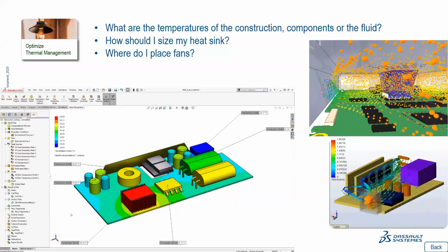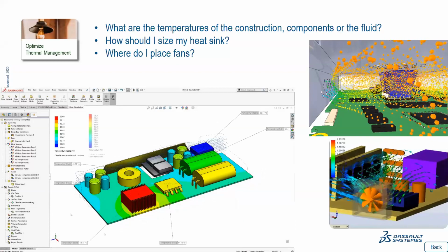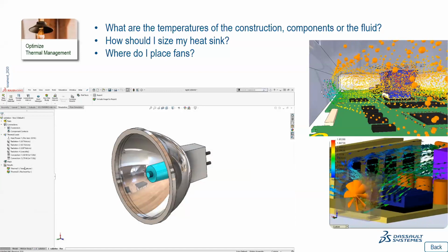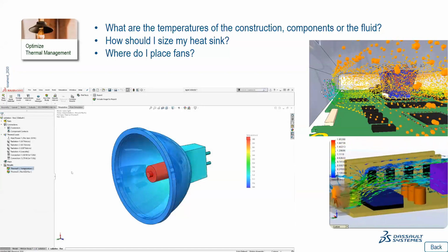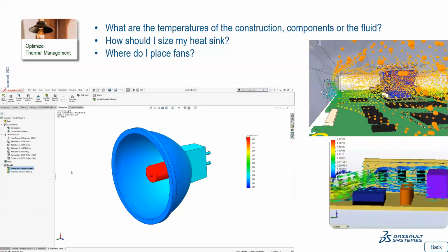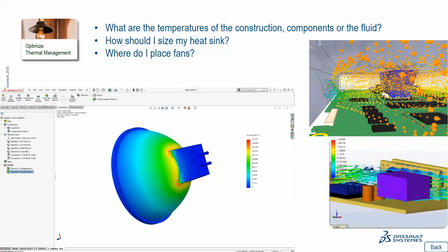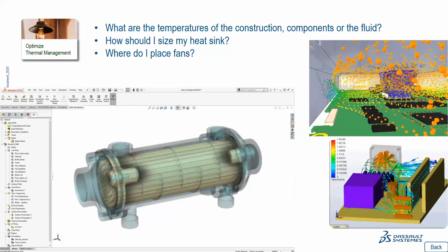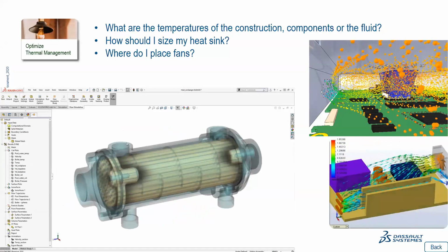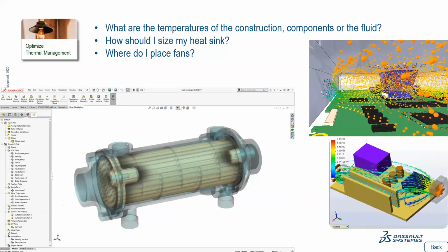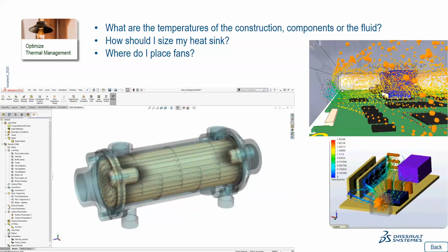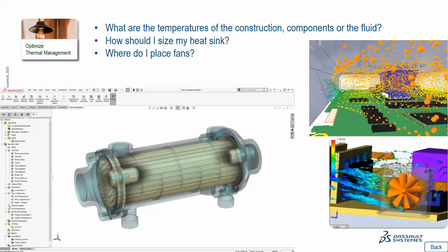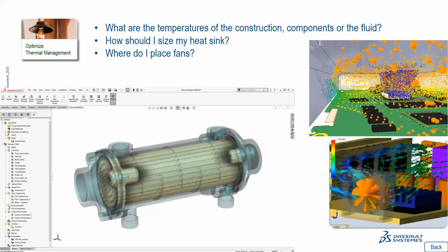Or also in the high-tech industry, everything which includes electronics will generate heat. So when you have this type of device, you can say, okay, I have to put one fan, maybe should I put two fans? Where is the best location to put the fan in my device? So I will optimize the flow, which will cool down many components, many condensers, many heat dissipators in my device. So this is something which is really very used in the electronic industry, the fluid simulation.